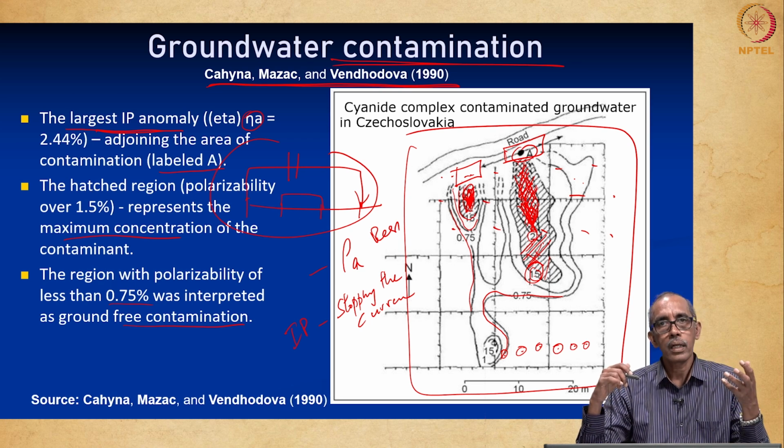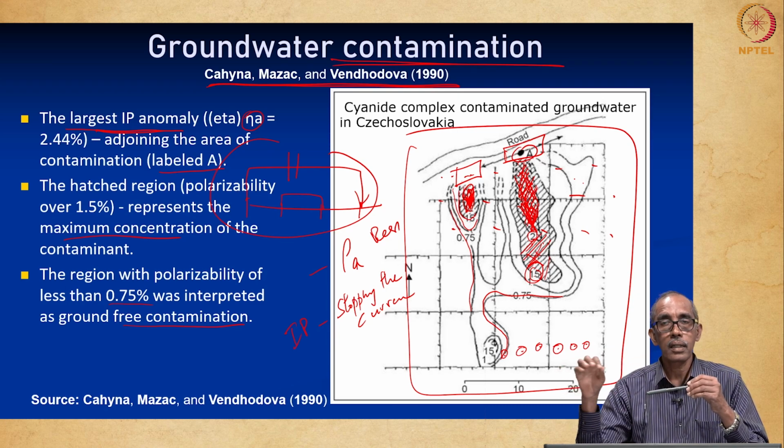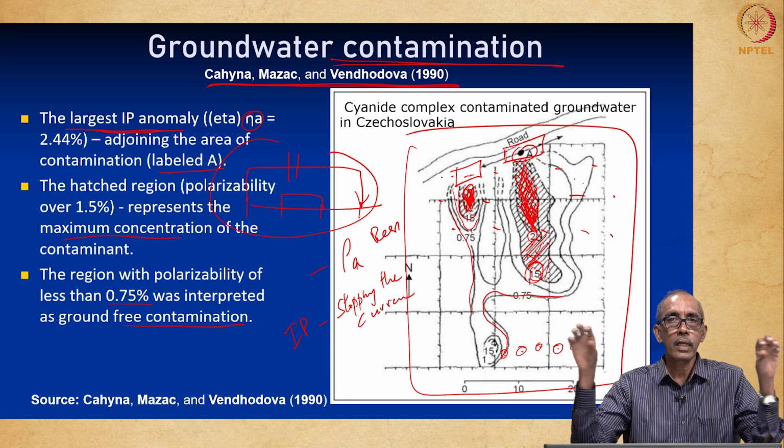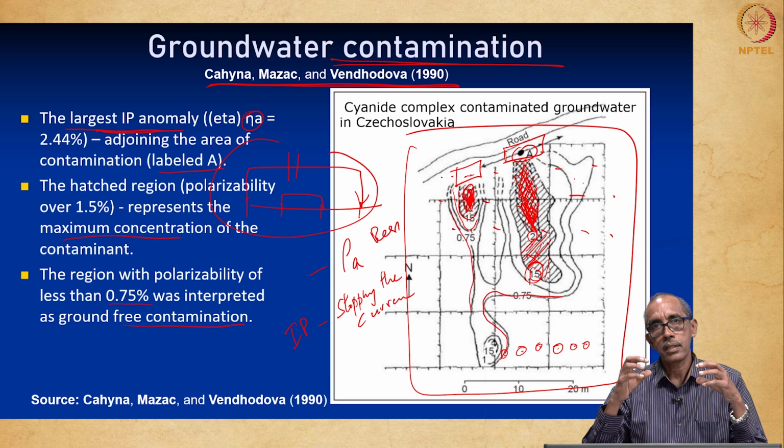Mostly it is groundwater, water, and the solids and mineral grains. If you have clay, clay performs in a certain way. If it is a metallic grain, it is completely polarized when you apply current. That itself becomes a small particle, positively charged on one side and negatively charged on the other. When you remove the current, it takes some time for the ions to realign and reposition themselves. Until that time, the earth remains charged. That is what we are making use of in the IP method.